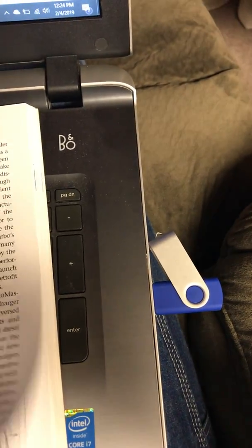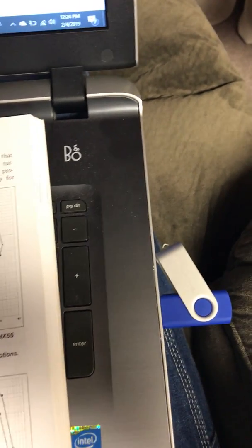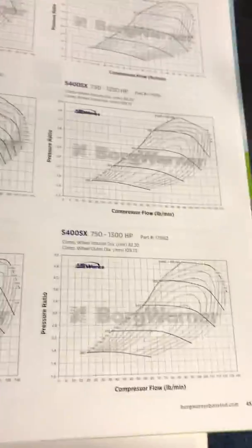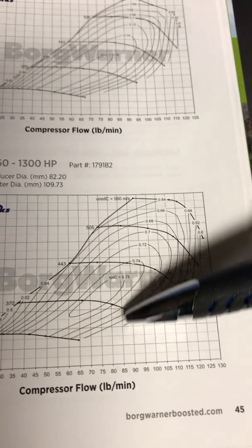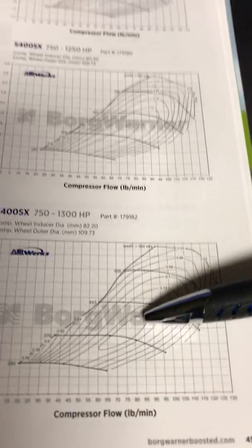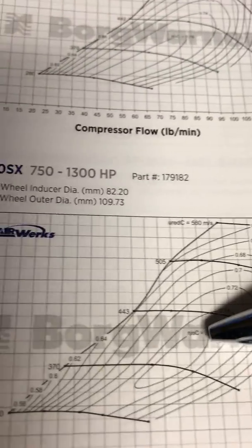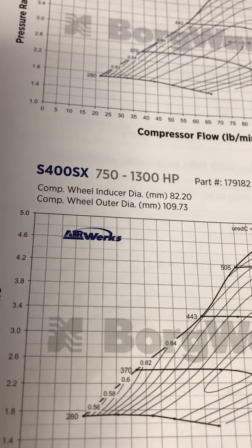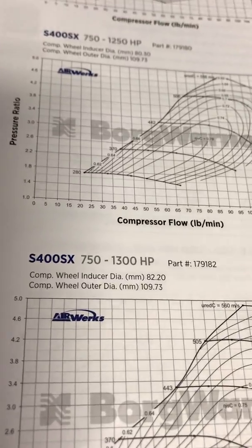Let me go back to the Borg Warner. I don't have the Borg. Actually, I do have it. Right here I do. Let's go back to this. So that's why, like, this new 488 is a bad dude here. Well, we don't even need to go to 488. Here's 482. 85 pounds a minute. Take it up to, let's see, this island here is 75% efficient island. Take it over to 2.6 to 1, and then you feed that into a smaller turbo to jack that up to get your 6 to 1 that you need.